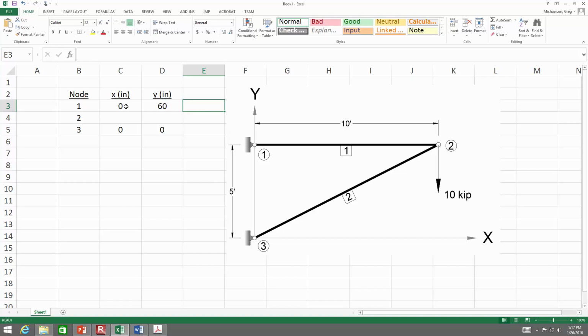And again, that's the same thing if you're dealing in SI or not, because it's real, attempting to express member lengths in meters. And then if you have an E value and it's in gigapascals, the appropriate length unit is probably millimeters. So you'd have a disconnect right off the bat. So make sure you're using consistent units with whatever you use. Okay? Now, so what are the coordinates of node number 2? 60 and 60, right? Sounds good, right?